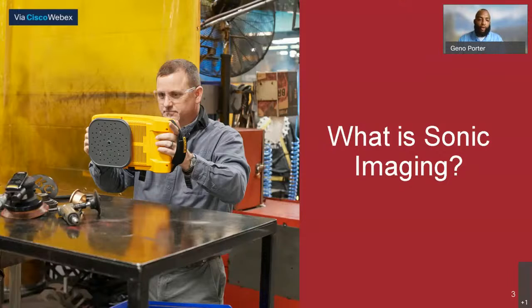So how does the thermal imager work? Basically, you take a device and you point it at something that has a heat source. For example, let's say you are going out to measure for hot spots on a transformer. You're looking at the bushings or where you make the cable connections. If one of those cables is a lot hotter than the other, that means you probably have a problem there. On the display of your Fluke thermal imager, it will show a big red spot, giving you a simple indication that something's wrong here.